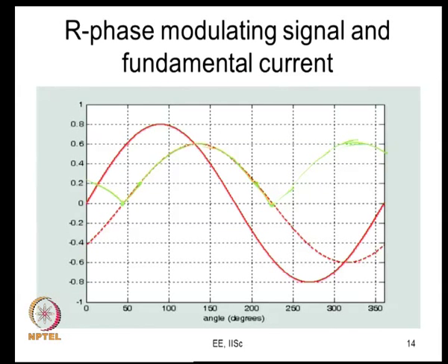Like this. This is your switching energy lost. And what is its average value? It is a rectified sinusoid. So, you can always say it is 2 by pi times its peak value. So, it is fairly simple to evaluate the average value here.